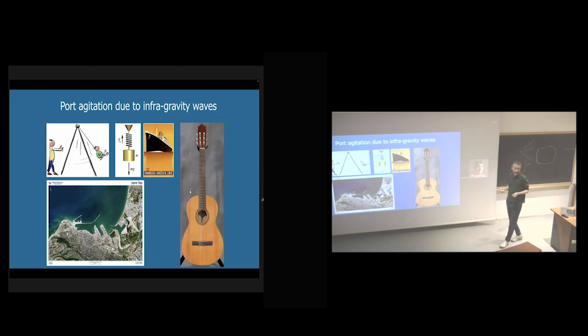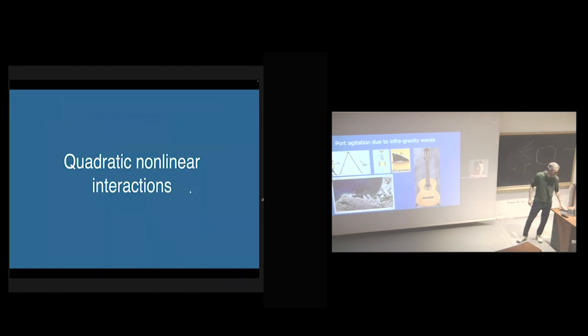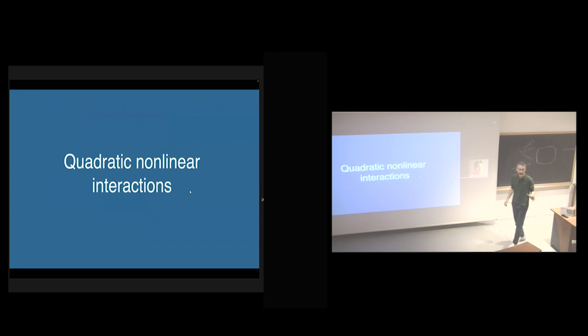They're also moored to the base. So if you are getting to their natural harmonics with these waves, you have a mess in loading them, and you can break, I don't know, the decks of the ships, and they can resonate with their moorings that are also springs and sway to the port. So that's kind of important for harbor design. Even if you have the harbor, you need to design the stiffness of your mooring system, just not to make it resonate.